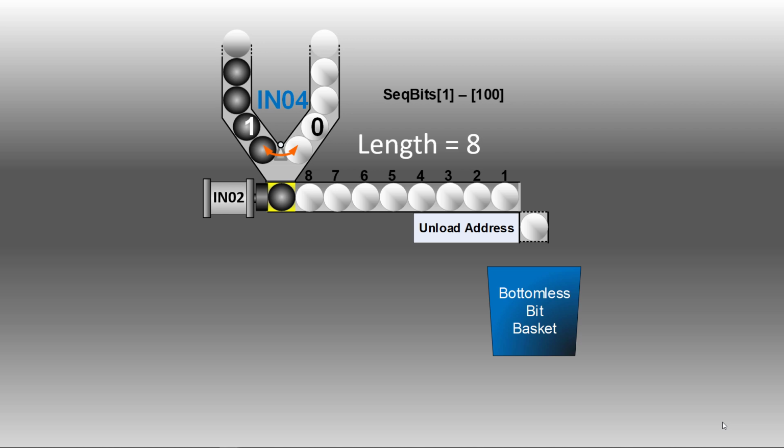However, if you have an offset of 0, then it will be the 8 bits closest to the least significant bit, which means it would be sequence bits element 1 through 8. If you have an offset of 2, then it's going to start with sequence bits element 3, and then take that and the next 7 bits. So you'll see that in the lab.